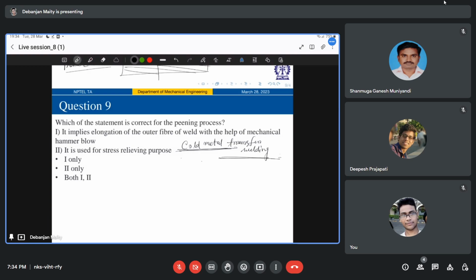So in terms of prevention, we can work with these things. In terms of remediation, residual stress once it arises in a weldment is relieved by post weld thermal treatment, right?